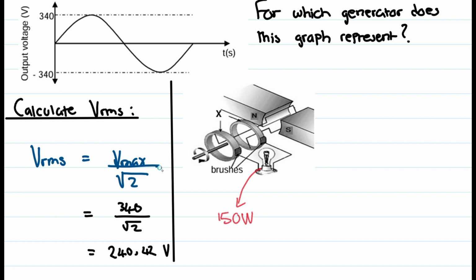So I do encourage that you take notes here, since we haven't discussed this previously. We have several equations with which we can do this. The first one is to find the average power. The formula for average power is P average equals V RMS squared divided by the resistance. What we are looking for is just the resistance.